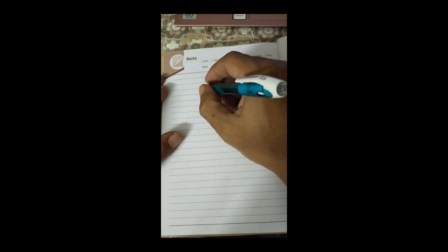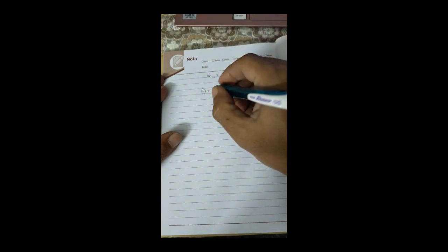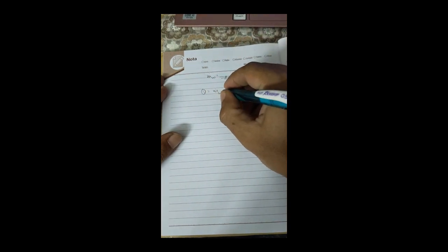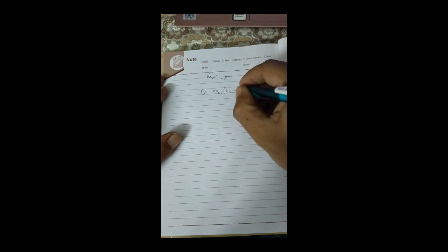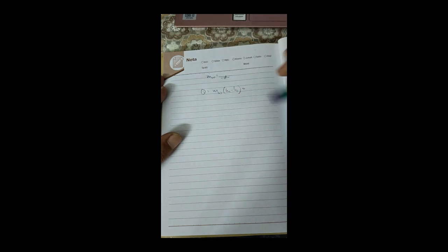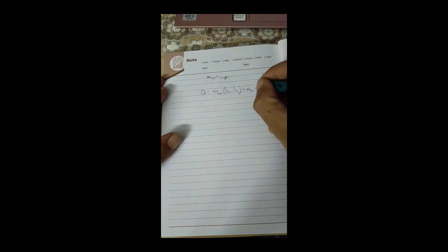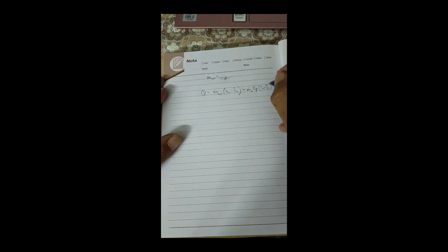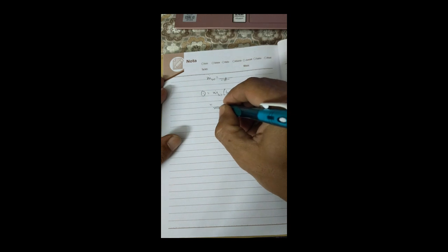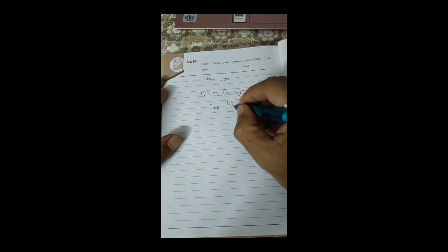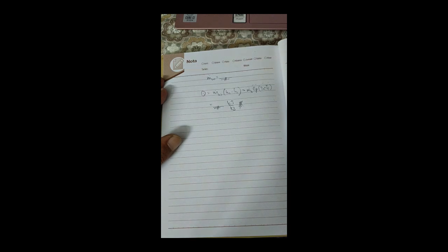Okay, for Q, the rate of heat transfer is m dot water (H2 minus H1), which is also equal to m dot sodium Cp (T2 minus T1). Either one, you have all the figures, so we can get your heat. Alright, okay, thank you.